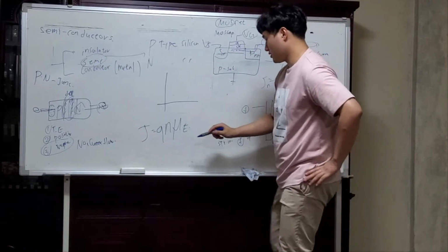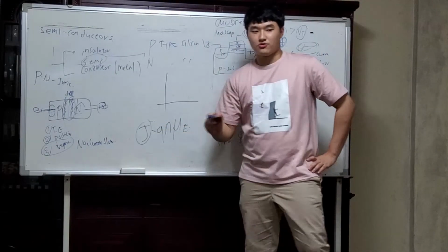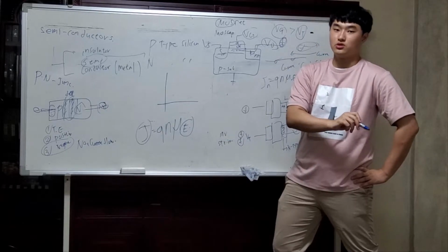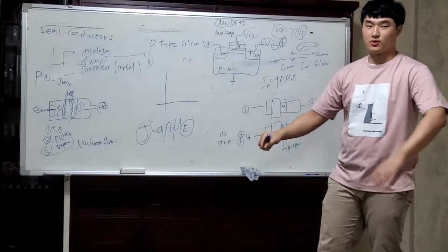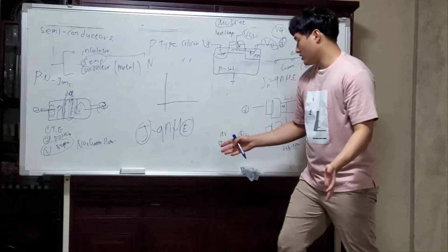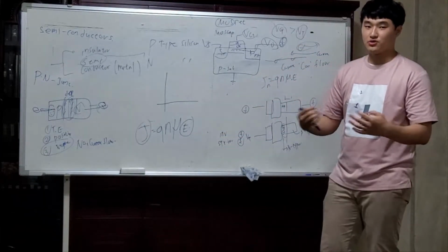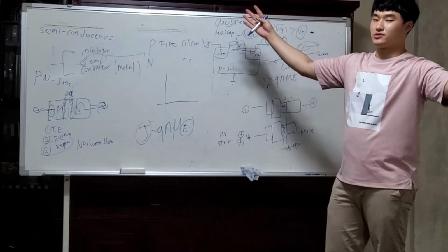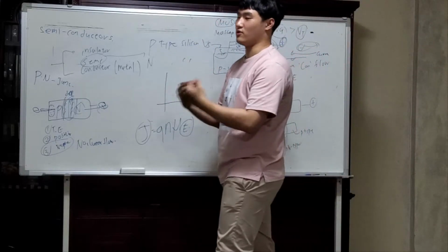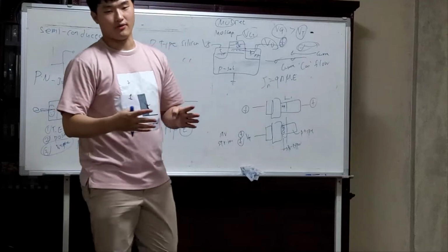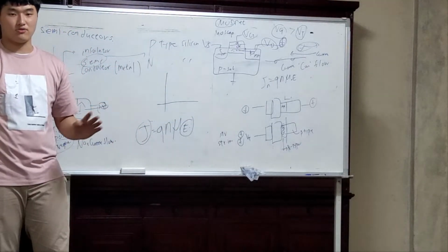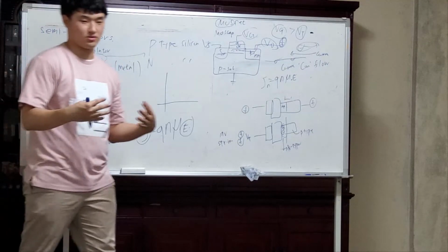The current flow density will be stronger if the electric field is stronger, in other words, if the voltage is stronger. And it means the current density will be larger. So more current will flow through the channel as the gate voltage or the drain voltage is enlarged.